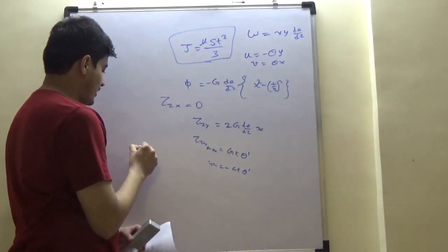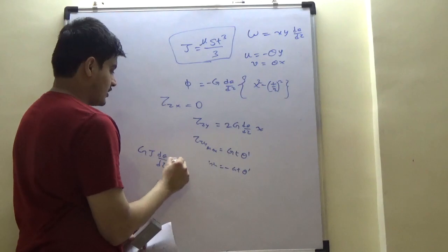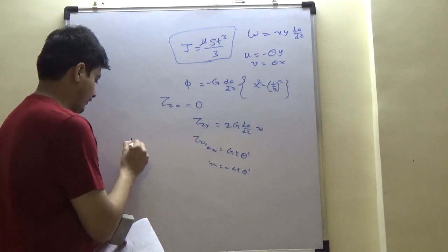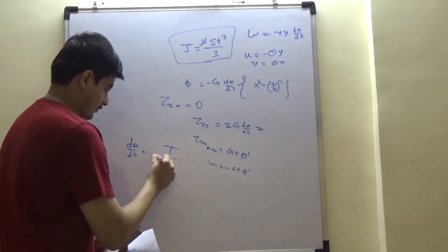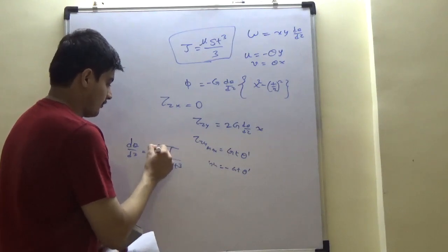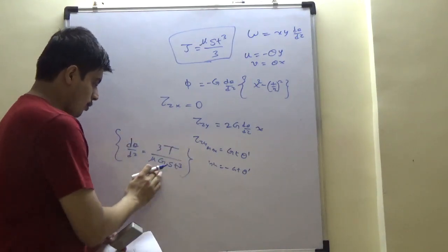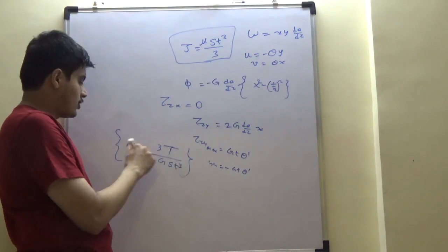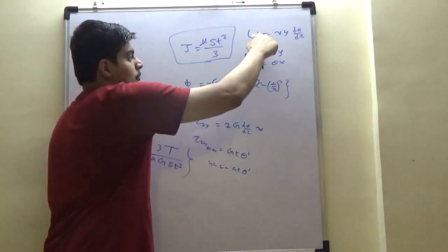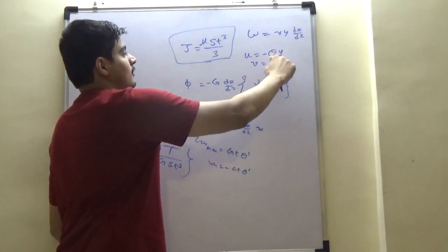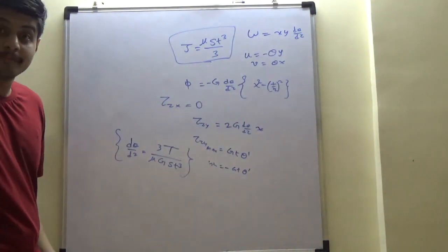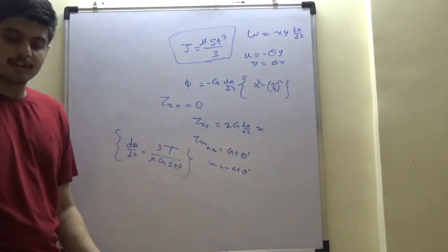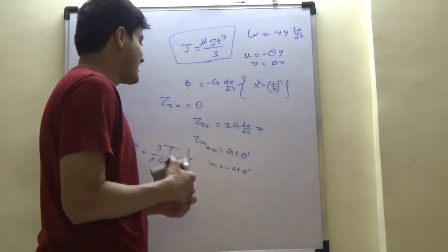Now, to note, G J theta dash is equal to torque. For a given torque, I also know d theta by dz. G S T Q, right? So the moment I substitute these known constants of my structure and loading condition, I know the rate of twist. I know warping. I immediately know based on this the components of U and V. Right? So see, I've solved this entire problem of thin sheet. And this was the third section of this property of why thin sheets are important.